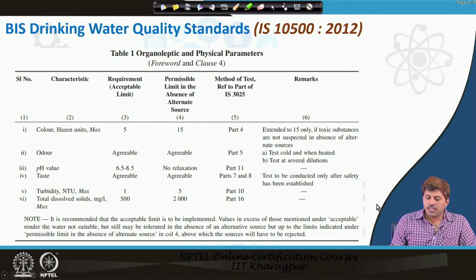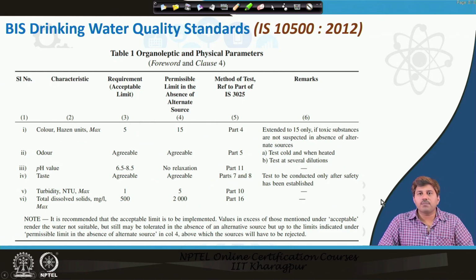Okay. So, TDS value is again one of the very important parameters which is considered for drinking water purpose, and you can see that it is quite high for drinking water, 500 milligram per liter, because we want essential minerals to be present in the drinking water. We do not want very low TDS water, like generally people do not drink distilled water. Okay. So, that is the problem.